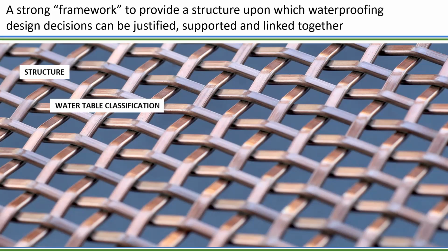Water table classification. I need to look at site investigation reports, the history of the building, if it's an existing building, things like that, to understand what the risk level, if you like, or the threat level is in terms of water ingress. The water table classification is important. We have high water tables, we have low water tables, we have variable water tables. All water tables can change, okay, depending on the time of year, and also, as I've alluded to, in terms